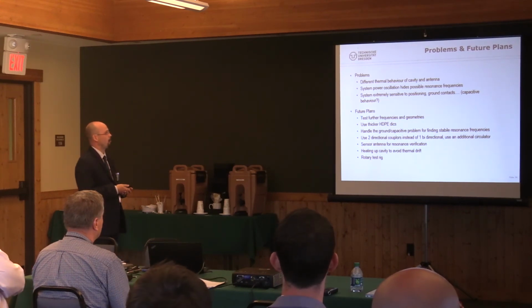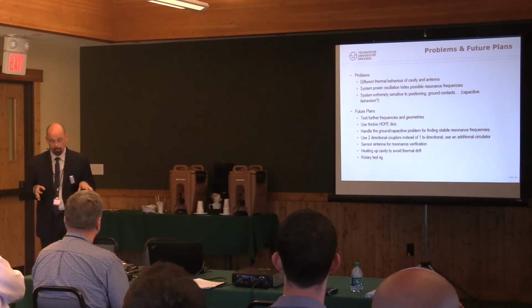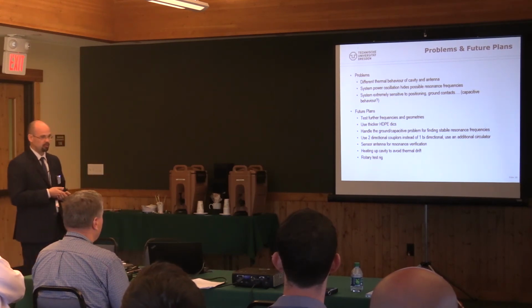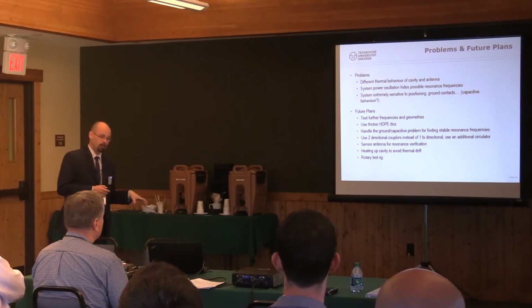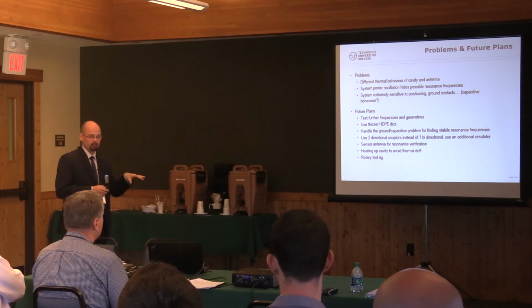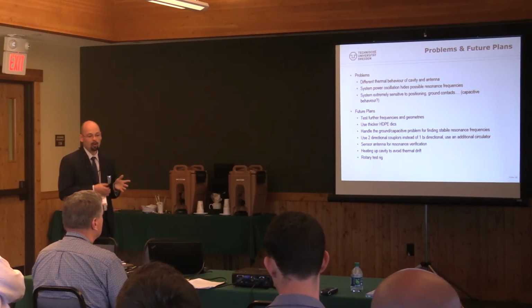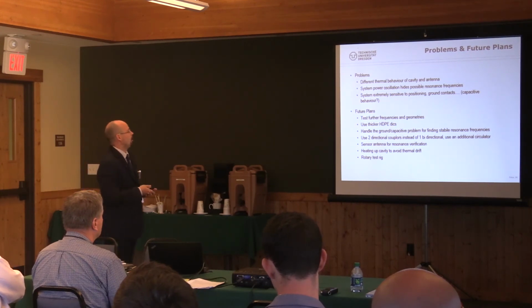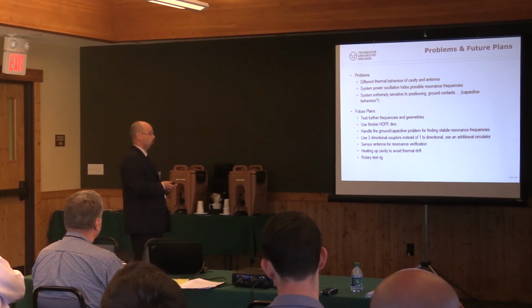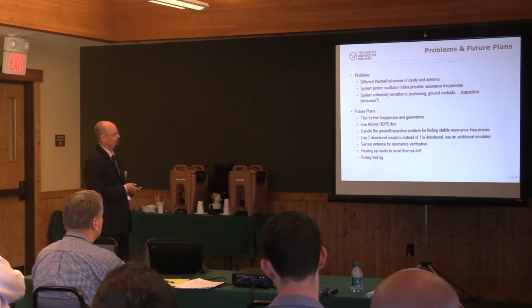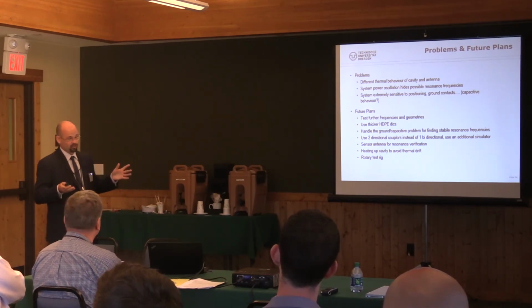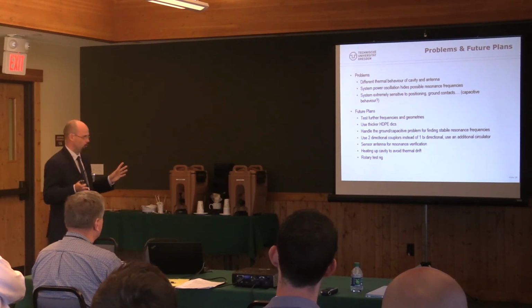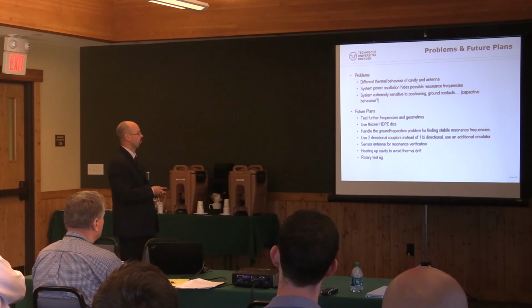I have clearly to care about this power oscillation inside of my setting. One way to rule this out will be using another circulator inside of a vacuum chamber next to my bidirectional coupler to avoid reflected power coming back from the cavity going to all our feed-throughs. And well, yes, the next problem, a really serious problem, is that our system is extremely sensitive to positioning of wires, to positioning of a cavity inside of our millimeter shielding box, ground contact, perhaps capacitive behavior. Who knows? I have to investigate it a bit deeper.